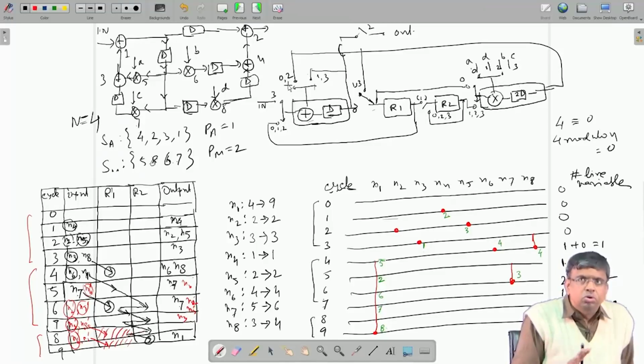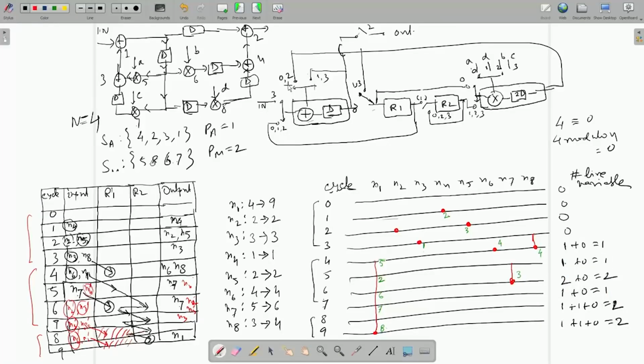Okay. So, here we stop for the folding part. We have done the folding of hardware units, then we have done some theory, retiming for folding, cuts and retiming for folding, so that no edge turns out to be negative. Then we went for delay optimization by folding, we considered lifetime analysis, lifetime chart, then forward backward data allocation, and finally construction of the circuits. We took some examples and finally worked out the same thing for a digital filter. So, I think we have given enough coverage of folding. We now consider the next topic.